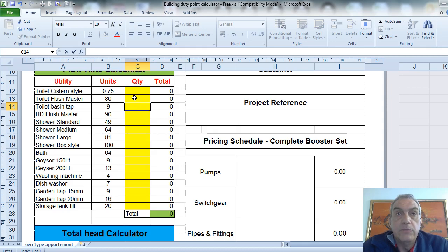It might take 25 seconds to fill 11 liters of water in a normal toilet cistern. So the refill rate, if you work it out, is 11 liters in 25 seconds. That gives you a flow rate which is considerably less than 11 liters of water in 4 seconds. Just do the calculation, you'll see how vastly different those two figures are. So what the spreadsheet does is it actually does that calculation for you.